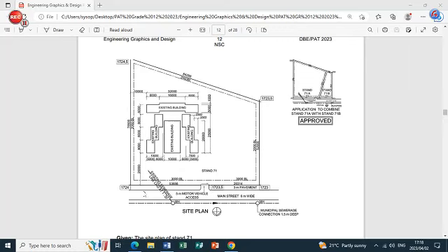And then you'll obviously see on the plan that there are the 4 corner heights. There's a building line on the inside there, and then we have a vehicle entrance with a 5 meter access point here, which leads into the main road, which has a width of 6 meters. There is a direction symbol on your site plan, of which this road part here faces north. So if that symbol is placed right in the center, this is going to be north, that is going to be south over here, this is going to be west, and that's going to be east.